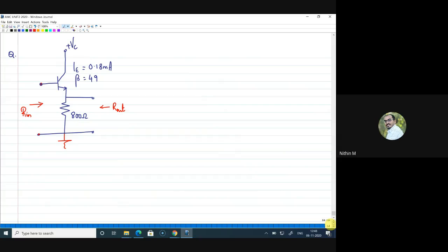So there is no resistance connected from emitter to ground. If I do that, that is an external resistance being added. But this RE is the internal model, we call it the RE model. Why I haven't brought the RE model into the picture is just to have a similarity with the analysis we have done for MOSFET. I can actually do it in a different way. What I thought is after doing all the analysis, I'll bring you the other way where I write in terms of RE. So just to avoid confusion, I did not bring it in the beginning.